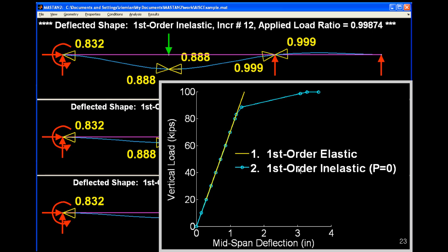Okay. So what was happening is, first of all, the program puts on the loads in increments. So let's suppose it's putting it on in 10% increments. All right. So it put on 10%, then 20%, and at each end of this, 30%, it goes and it evaluates the structure to see if it has any full yielding anywhere. Nope. All right, now let's go to 40%. Any yielding? Nope. Eventually it got to 80%. It still had no yielding anywhere. And then when it went to go to 90%, what it found is midstream in that load step, a plastic hinge would have formed at that left end. So the program automatically scales back the load step, so it's only 83% of the load. It figures out when it would occur, and then it puts in the plastic hinge, and then you start moving from there. So it put in the 83%, it put in that plastic hinge.